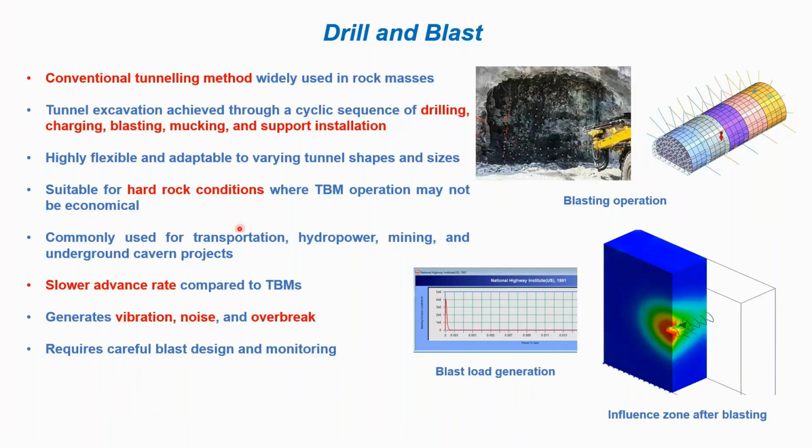So these are also commonly used for transportation, hydropower, mining, and underground cavern projects. However, their advance rate is slower as compared to TBM, and they may also generate vibration, noise, and overbreak. So it requires careful blast design and monitoring.